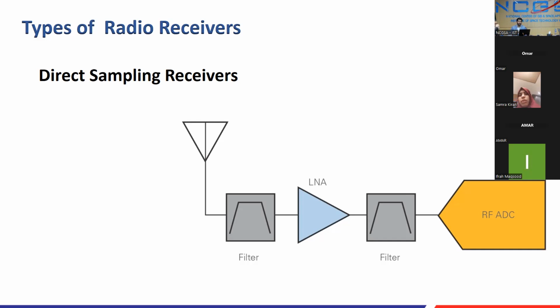Well, in a superheterodyne architecture, as we move forward, I will share a practical example as well. Usually in most of the cases, only one of the LOs is tunable. The other one is fixed. The first one, the tunable LO, is usually used for producing the 2 sidebands. Then you have a band stop filter that rejects the image.